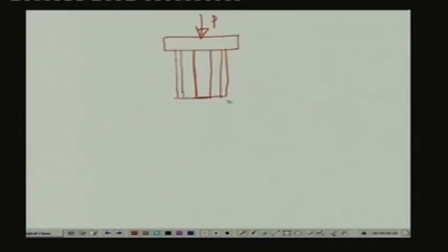So, in this free body diagram, if we now transfer the reactive forces acting on this, they are the force in the copper rod and the force in the sleeve, these two together. Let us call the load in the aluminum P aluminum. So, we have these two forces, P C and P aluminum, which are being generated because of the externally applied load P.